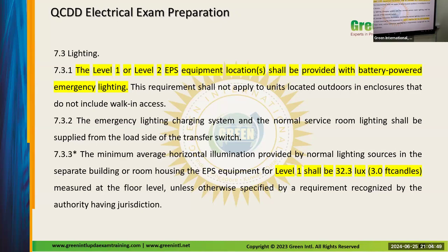So simple: if you have a question related to lighting, first priority, refer to 101, chapter 7, that is egress. There you can find the answer for the entire topic, because for emergency, you definitely refer to the egress systems. For life safety, you refer to that irrespective of all other standards. Even though you can find the answer from 110 and 101, instead of 110 you prefer 101.